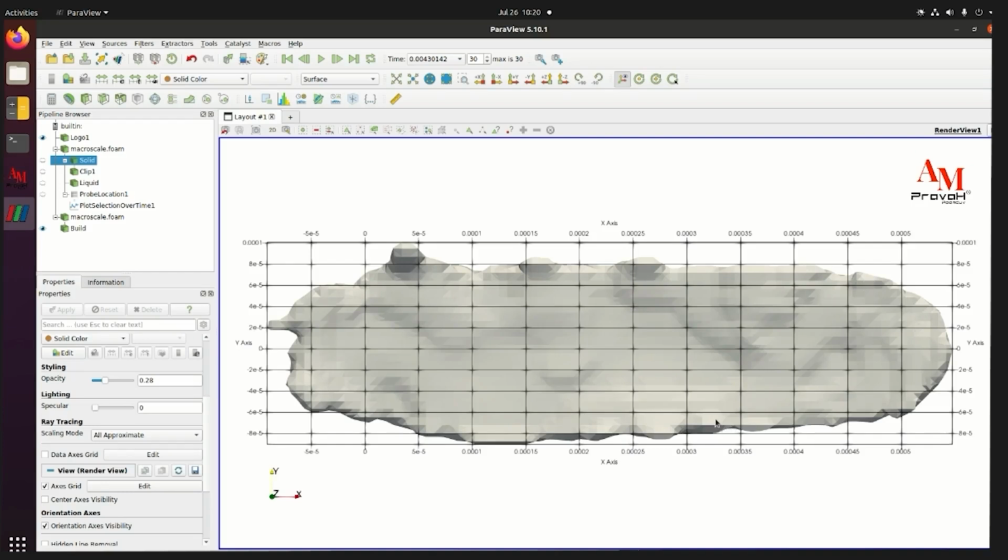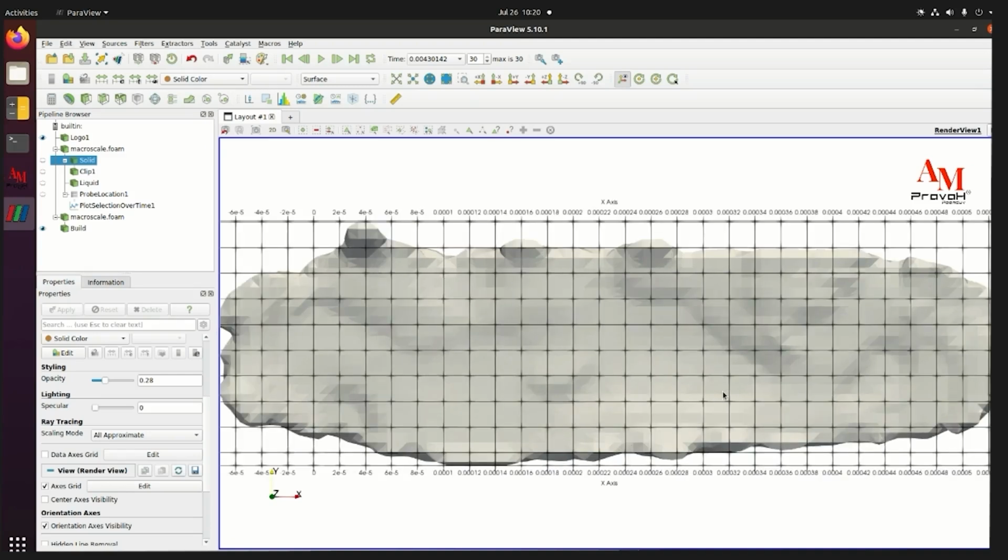So now it's a little bit subjective, but we cannot take the width here, because here just the melting started, and obviously the simulation takes time to get established. And now, somewhere where the width started getting a little bit stable, that point we can take, and that point is like 0.0028. So that value you can take.